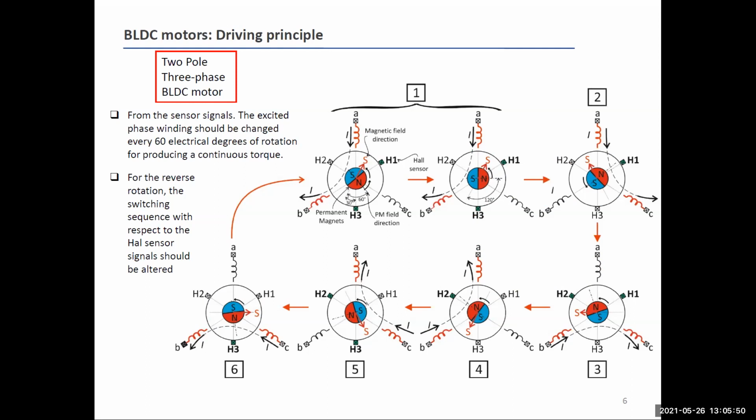etc. Remember that the original goal that made possible the development of a brushless DC motor was to change the architecture of a DC motor, avoiding brushes, mechanical fixtures, etc. Now I'm discovering that in order to generate a continuous torque, I need to add something. I can avoid the brushes and the commutators, but I have to add Hall effect sensors. These are semiconductor devices, so they are not as unreliable as the brushes or the mechanical commutator that you add in the DC motor. But anyway, the cost is a little bit increased.